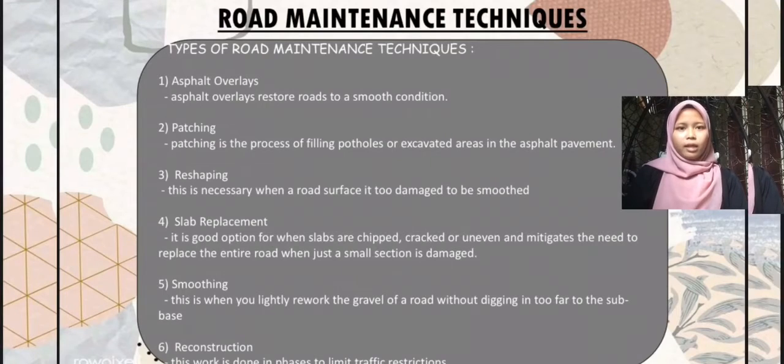Okay, next I will explain about road maintenance techniques. There are many types of road maintenance technique. First is asphalt overlays. Asphalt overlays restore roads to a smooth condition. Second is patching. Patching is the process of filling potholes or excavated areas in the asphalt pavement. Next is reshaping. This is necessary when a road surface is too damaged to be smooth.